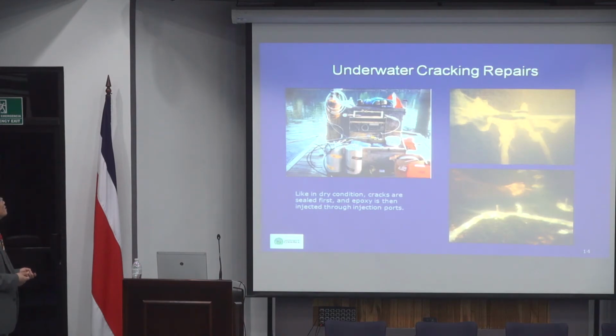You can do underwater repair, for example, using epoxy to seal a crack. You can also use epoxy materials to repair spalling, that kind of thing as well. But the quality is not as good.